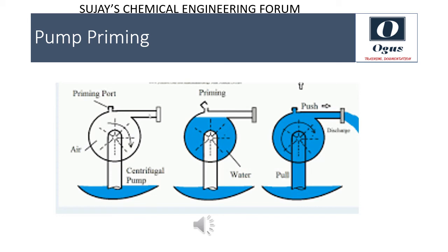The way to overcome this problem is priming the pump by opening the suction valve and letting the liquid fill the pump casing until a steady stream of pure liquid, without any gas bubbles, comes out through the top vent port or priming port on the top of the pump casing. In case of handling hazardous fluids, it is recommended to divert the liquid stream to a closed drain system.